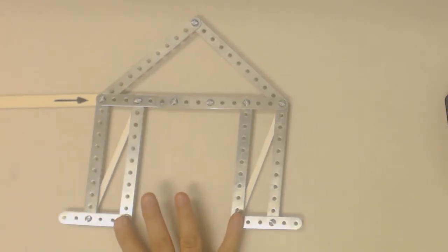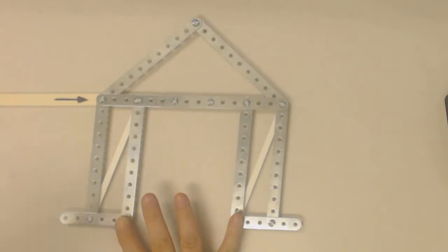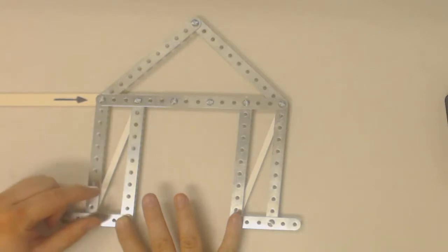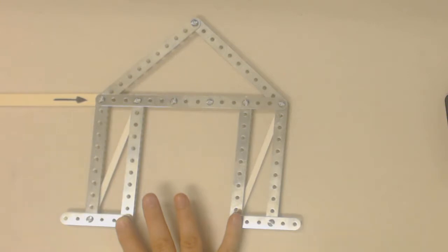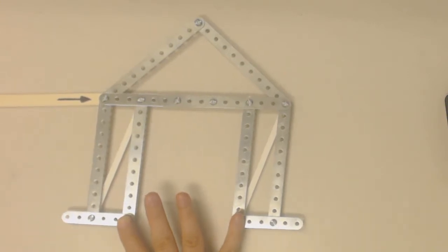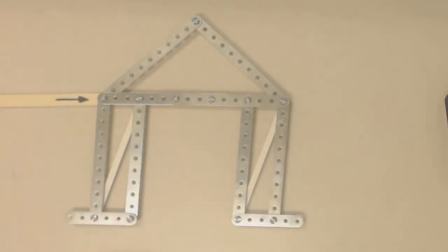If we have a 20,000 pound lateral force being exerted on our structure, like so, that 20,000 pound force has to be resisted now by these diagonal braces. And you'll notice that the angle that these braces make with respect to the ground are quite a bit larger. These diagonal braces are quite a bit steeper. We're going to use this in our next analysis to see how the forces in this whole thing change as a result of this 20,000 pound load.